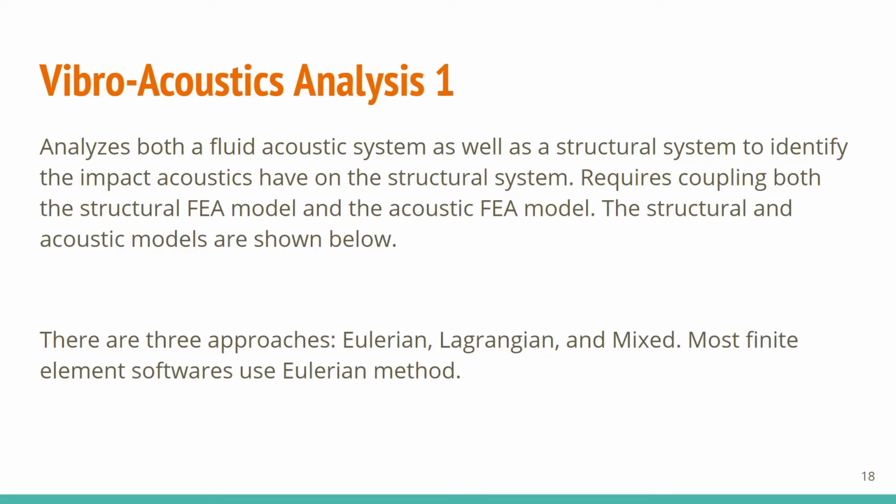Now, vibroacoustics analysis, this is important in that if you want to model a system where you have an acoustic fluid interacting with a structural boundary. So this requires both the structural FEA model and an acoustic FEA model. The structural and acoustic models are shown in further slides. There are 3 approaches to this, either Eulerian, the Lagrangian, and the mixed approach. Most finite element softwares use the Eulerian method mainly because it is the most accurate, but it's definitely one of the harder methods mathematically to derive.